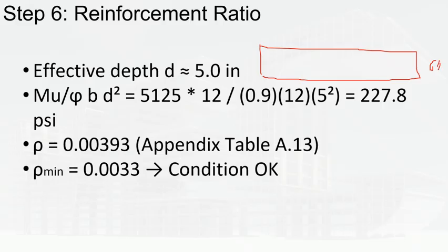We said that that's the height of our slab. Now what exactly is the depth? The depth is the height of the slab from the top till your bars, till the half of your bars.